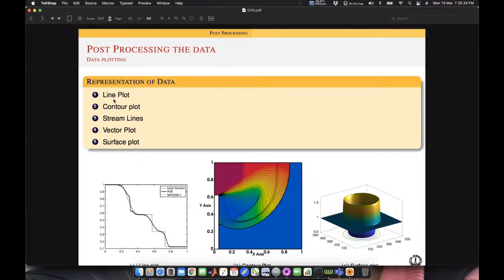If you see the second figure, there's a shock wave propagating from the diverging section, from the 90-degree point at a corner. You can see an expansion fan, a contact discontinuity, then a shock traveling. All these things are represented properly from the contours of the data that you are looking at.